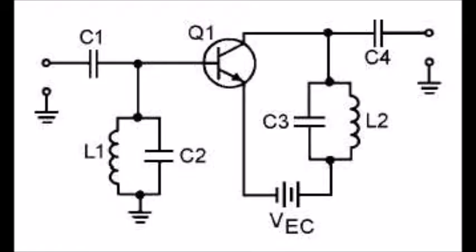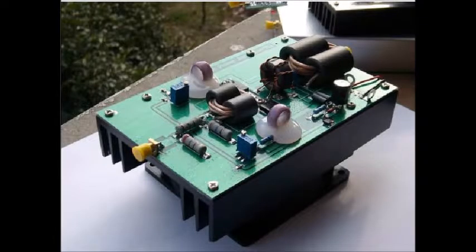Now coming to the working of the RF amplifier, let's explain. Since the detector works more efficiently with a larger signal applied, we should first amplify the signal before feeding it to the detector. An RF amplifier amplifies the radio frequency signal. The frequency at which maximum gain occurs in an RF amplifier is made variable by changing the inductance or the capacitance of the tuned circuit. An RF amplifier can tune over the desired range of input frequency.